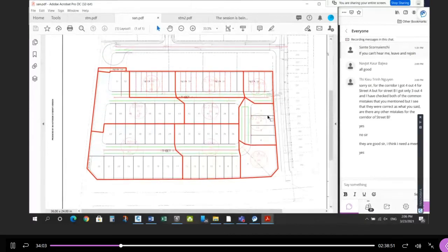Okay, so that's the kind of rationale I was looking for here. Did you delineate correctly? Did you put in all the drainage data, all the bubbles with the areas and the populations? And did everything get cut up properly? And then for presentation's sake, did you show only what is meant to be on a sanitary drainage plan, i.e. no grading, no storm, no water main, existing and proposed. All right, so this was 3 marks for the design delineation and data, and then 2 marks for the drafting. Did it look right?